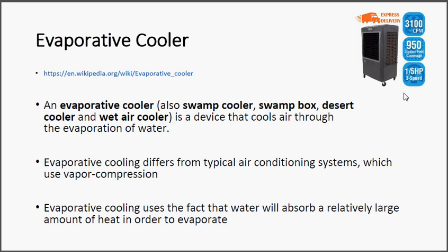If you've got a traditional aircon unit, a mobile or portable one, you would have a big pipe at the back of it, and you would have to pull the pipe out somewhere, and blow the warm air outside the area which you want to cool down. With an evaporative cooler, you don't have to do this.